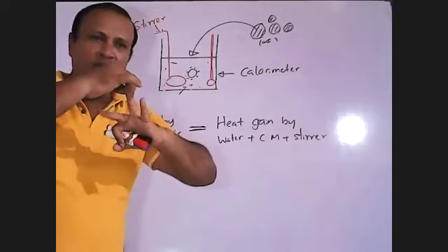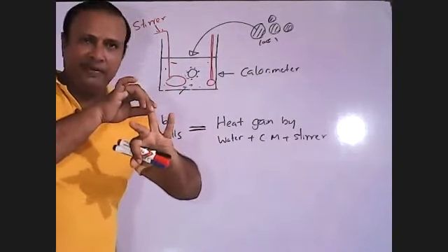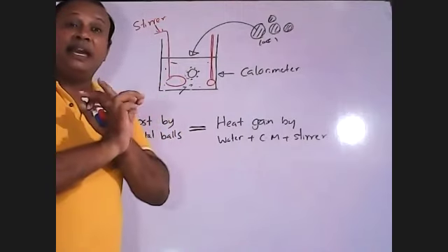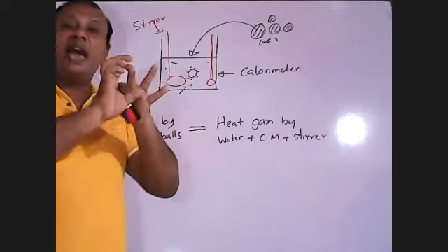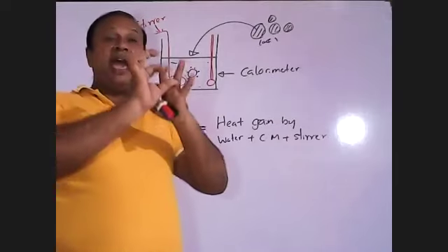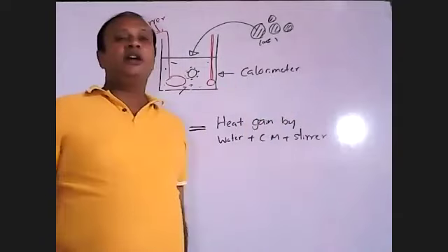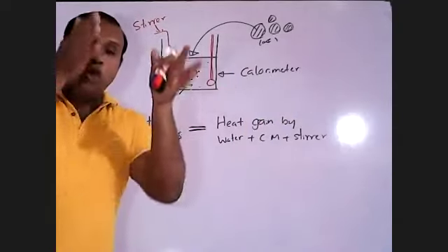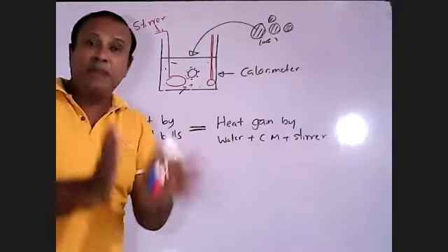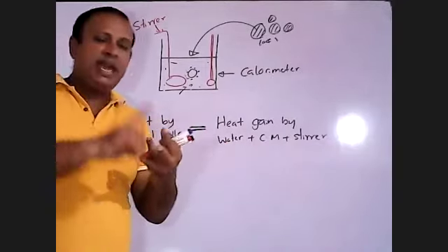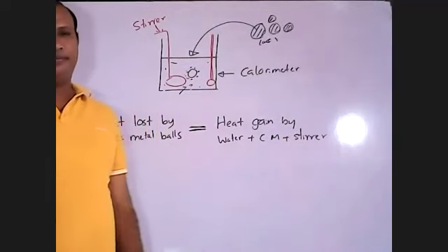Normally, the C value is a given data. The other two, that means the mass and the temperature difference, should be measured during this practical. Therefore, you should organize this practical to measure the mass values and the temperature difference.